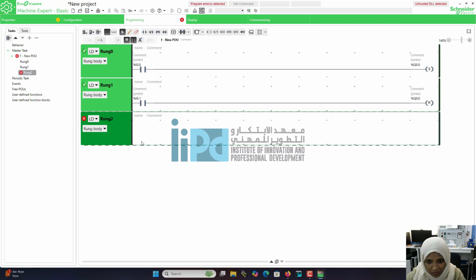0 to 1 means whenever the process is in the off condition, suddenly the process turns on, or some inputs turn on. All of a sudden, there is a change from off to on, or from 0 to 1. If you want to detect that change, that input can be given to a positive trigger. This positive trigger will generate a pulse. So you can detect that particular change, or use it as a trigger to send and receive signals. When you work with communication protocols, for each pulse I want to receive a signal. For that also you can use it.